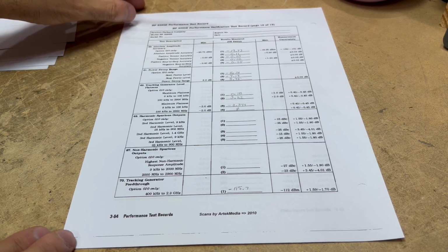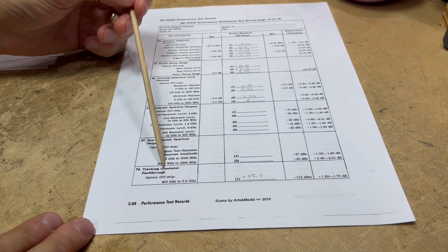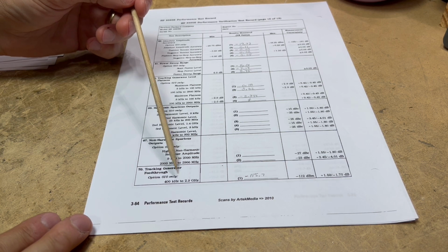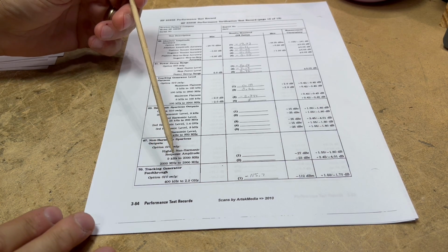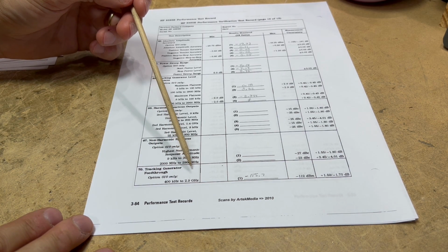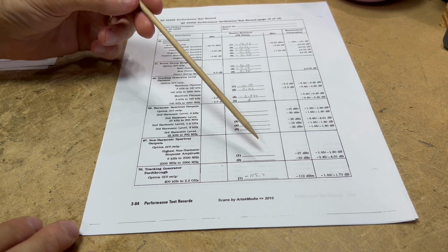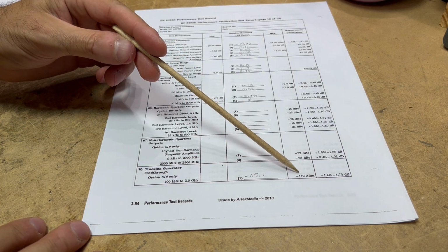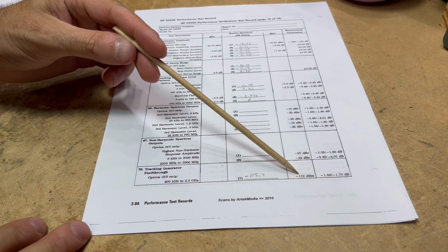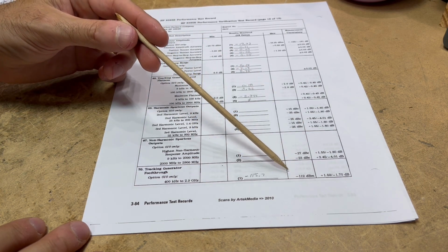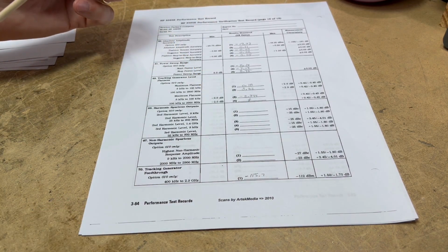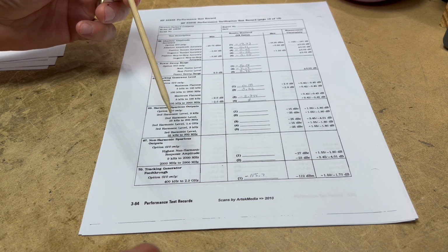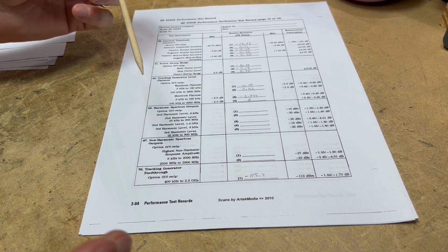One thing I was able to correct, though, is tracking generator feed through. I took the measurements initially and found that I had some feed through at 2.6 gigahertz and 2.9 gigahertz that were above the allowable feed through level of minus 112 dBm. So I took the whole tracking generator RF assembly out, and the problem was that when I had originally put the modification in, I didn't use rigid coax.